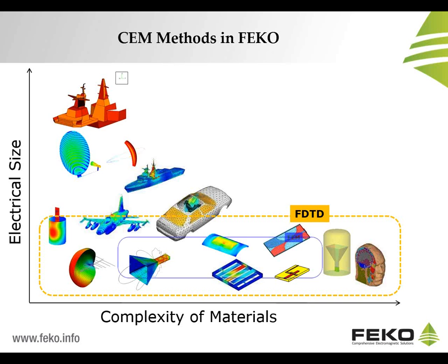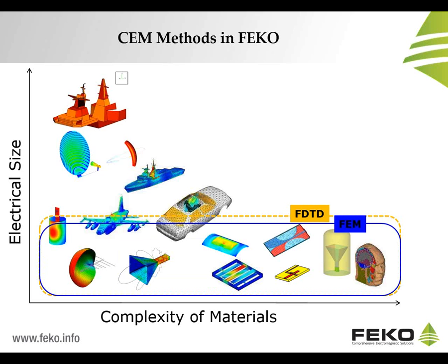The same can be said for the FEM or finite element method, which is a frequency domain method and is also a method that meshes the volume of the entire problem. In the same way as the FDTD, the finite element method is well suited at solving complex dielectric problems, but as you can see by the indicated boundary, it is not very good at solving electrically large problems.